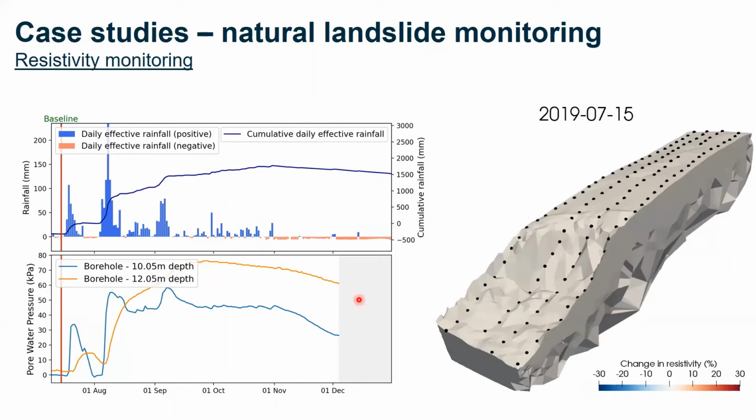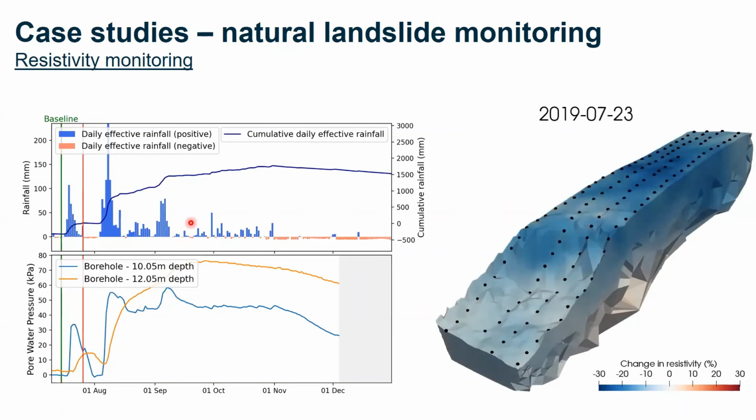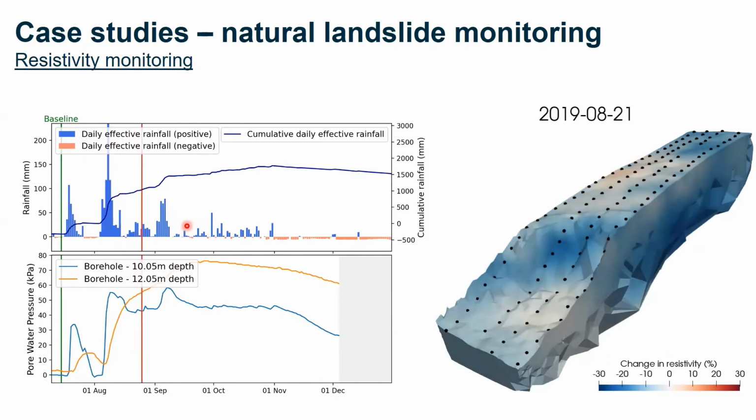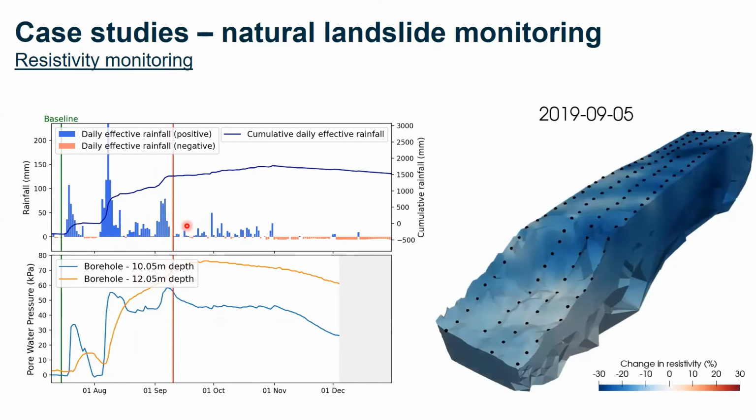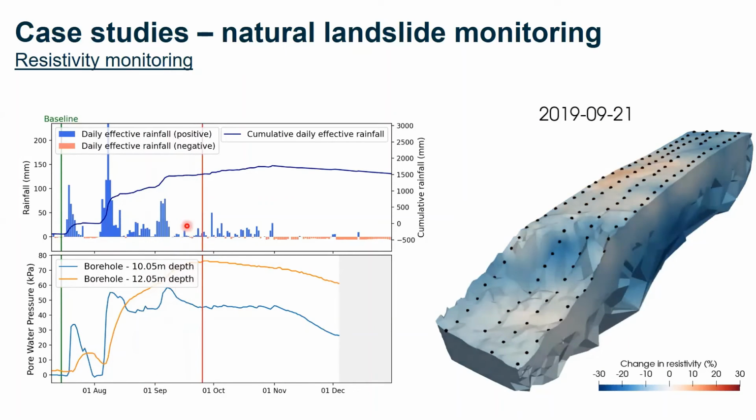And as we go through these three main rainfall events in the monsoon season, we'll start to see these wetting and drying phases that the slope experiences. So first event, then it dries up, then a second at the peak of the monsoon. And then as we go through the dry season, we start to see progressively the whole slope, which dries up.